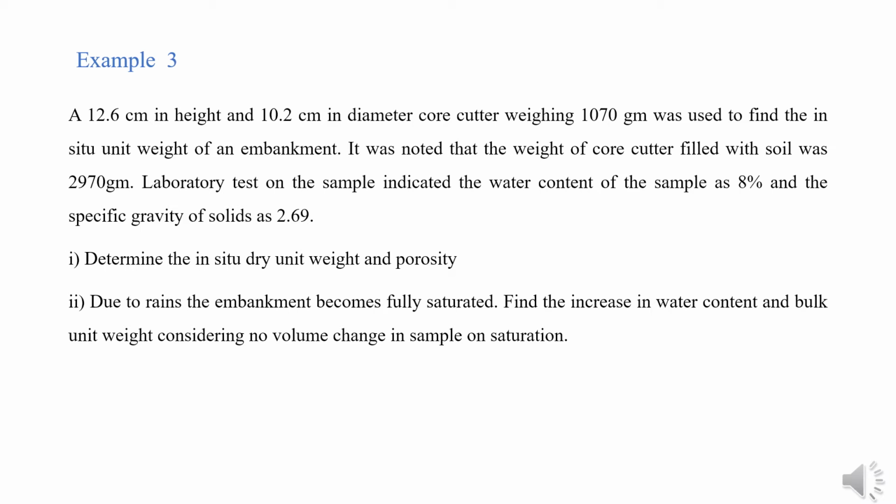So this is our next problem. Let us try to solve this. A core cutter 12.6 centimeter in height and 10.2 centimeter in diameter, which weighs 1070 gram, was used to find the in situ unit weight of an embankment. It was noted that the weight of the core cutter filled with soil was 2970 gram. The water content of the sample is 8% and the specific gravity is 2.69. So we have to find the in situ dry unit weight and the porosity of the sample.